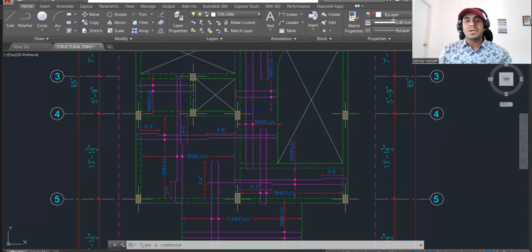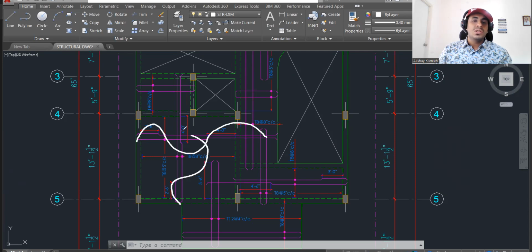First, you tell me the bending moment diagram. Let me see, if you draw the bending moment diagram only, you will be able to understand. So again, you'll be having a negative bending moment. It will be positive, then it will be negative like this. Similarly, here it will be negative, then positive, and again in this portion it will be negative. Why? See, wherever there is continuous, you will be having a negative.